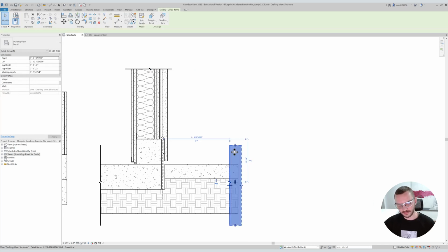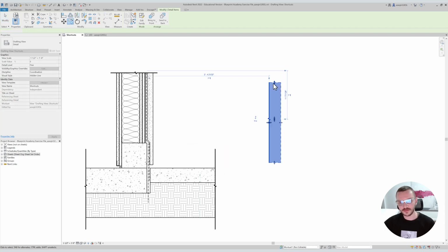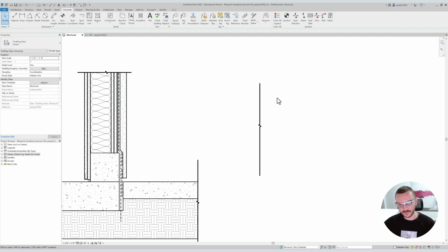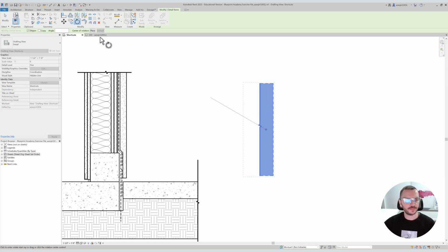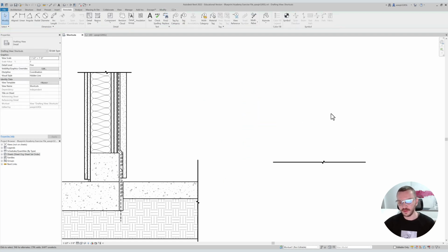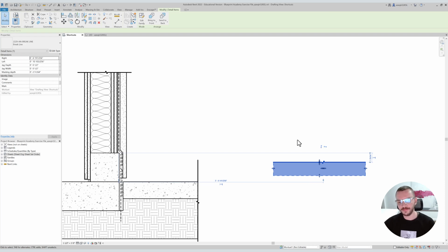Although rotating, by the way, if you need to rotate, you hit RO. Instead of placing the center of rotation, you can hit spacebar, and then select where you want to rotate it from, and then just type in what you want, and bada bing bada boom.